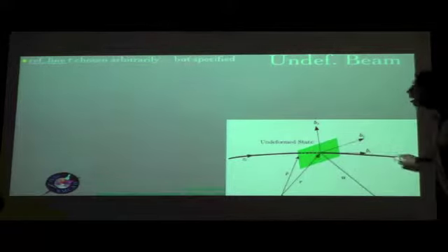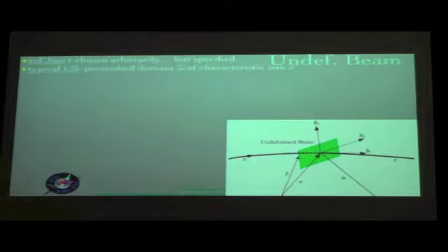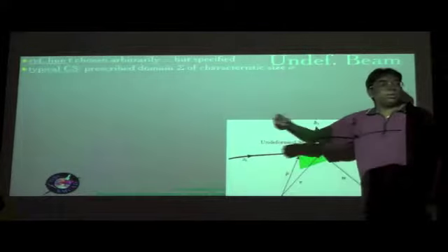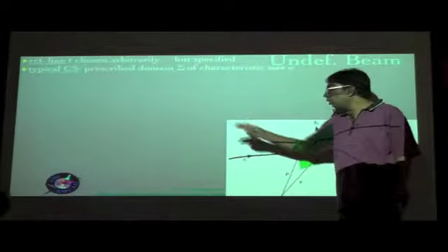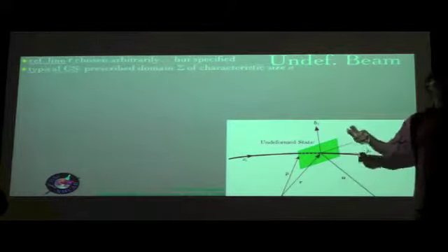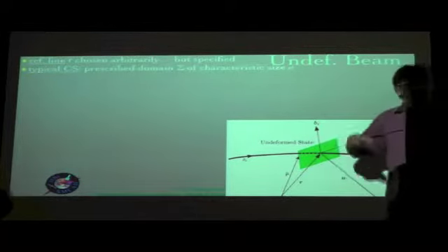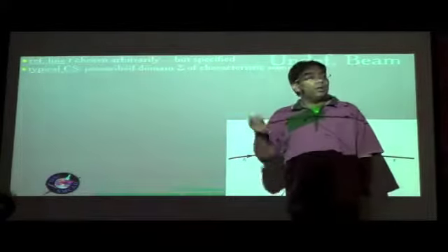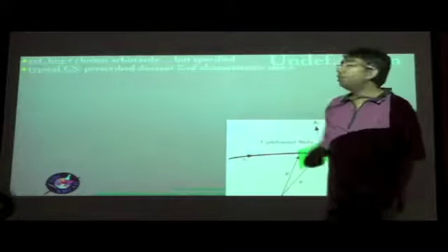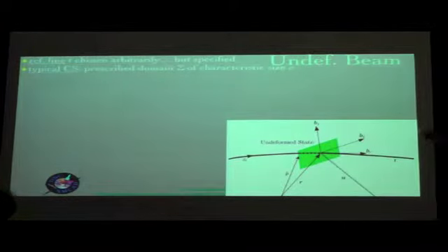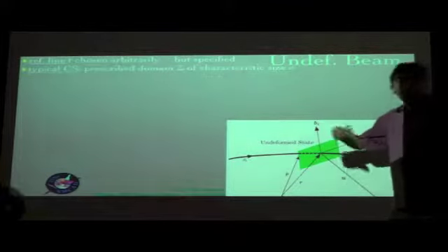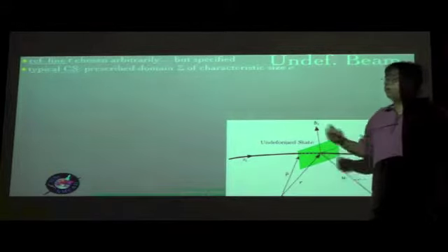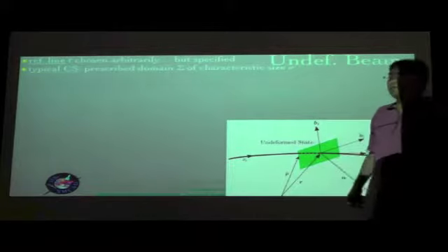The reference line, once again, R, is chosen arbitrarily, but it has to be specified. In other words, you have to specify it as either the loci of the centroids or the loci of shear centers, whatever, but that has to be prescribed a priori, because depending on that choice, the meanings of all these 1D variables that we introduced, for example, this small gamma 1, the kappa 1, kappa 2, kappa 3 can change. Okay, so that's the reason why it's important to define that. And depending upon what you're actually trying to find, certain choices of R might be more prudent in terms of making your derivation less complex.